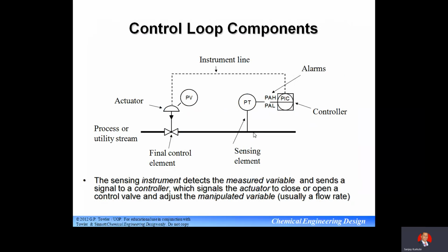Here in control loops, there are normally feedback and feed forward types of control loops. In a feedback control loop, the changes in process output are measured and the manipulated variable is adjusted to return the output. Whereas in a feed forward control system, it measures the disturbance and adjusts the manipulated variable to compensate for it, so that the control output will not be affected.